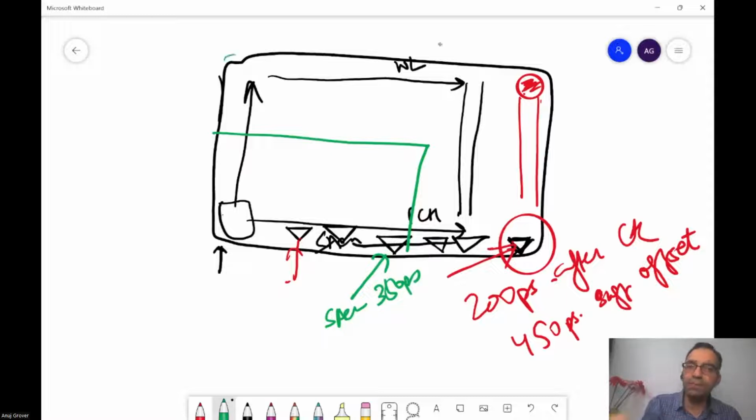But when the memory instance is a big one, I want it to be later. If the memory instance was still smaller, it can come at even 250 picoseconds, and so on. So I want there to be some dependence on memory size. Depending on whether the memory is big or small, the enable signal should come sooner or later.